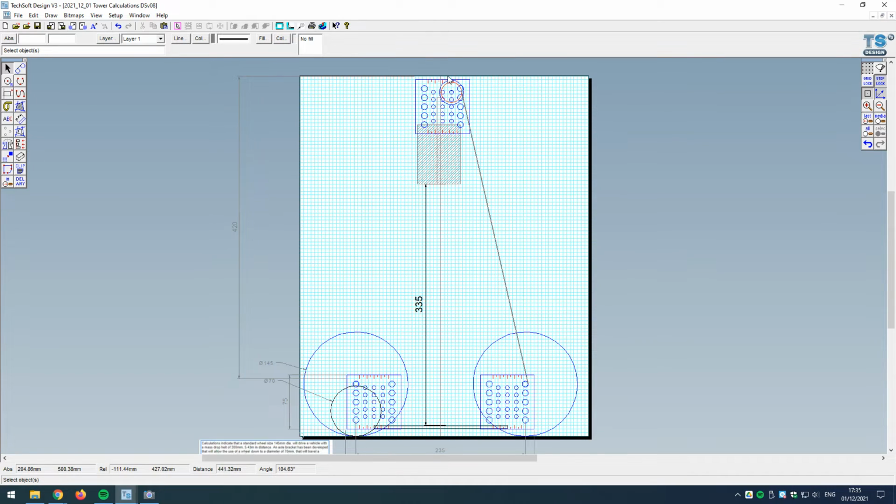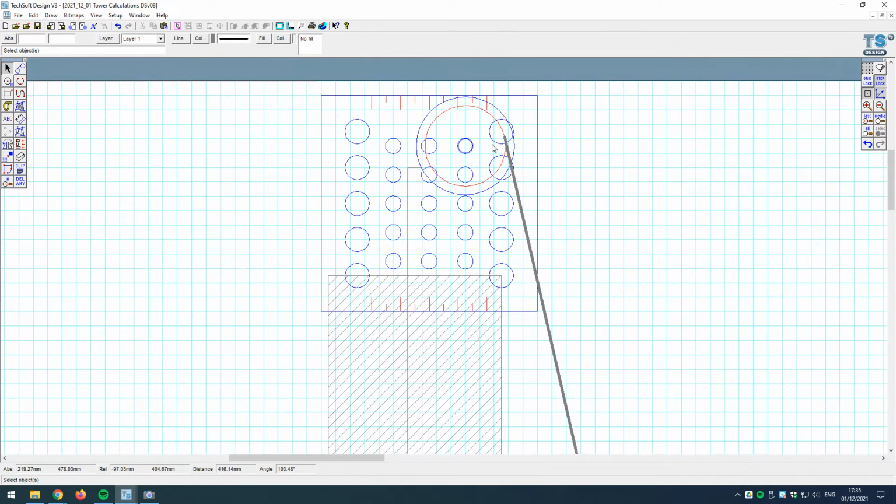While I'm looking at this, I'm also quickly going to talk a little bit more about what's happening with this top pulley. We've got a series of holes here in this axle bracket. This is a universal axle bracket. And if I just identify the size of the hole that this pulley axle is running through, the actual axle itself is 5 millimeters in diameter, and the hole is 5.4, and that's to allow minimum friction as the axle turns in the axle bracket hole. If I put it to 5, of course, it probably would have jammed. Okay, and all these holes here are 5.4 millimeters.